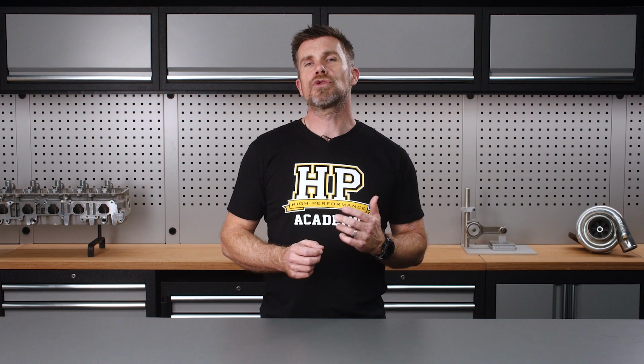Let's have a quick summary of things so far. We're trying to find the amount of ignition timing we need to get cylinder pressure to peak at around 16 to 18 degrees after TDC. We've learned that combustion does take some time, and the speed of combustion will depend on a number of aspects, including cylinder diameter, compression ratio, the design of the cylinder head, and whether the engine is using forced induction. This information helps us understand why different engine designs need different ignition timing.